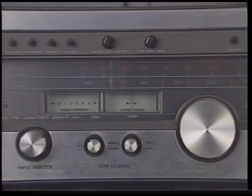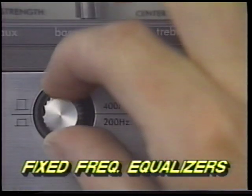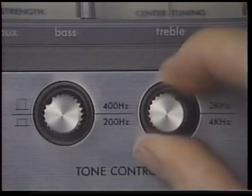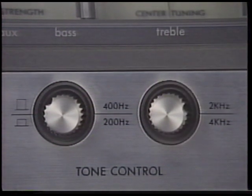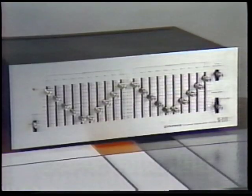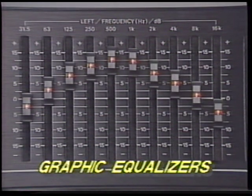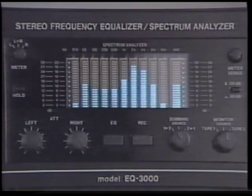The simplest equalizer has a fixed single frequency, but you can vary the amount of attenuation or boost. Many small boards have simple 2-band equalizers with a few selectable frequencies for each boost or cut control. Graphic equalizers have the ability to boost or cut at specific frequencies. Most of them operate across the complete audio spectrum, but some will encompass a smaller range.